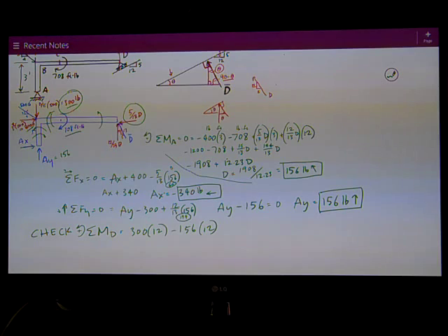I should probably reverse this arrow on my free body diagram for AX. It's going to the left, which is going to create clockwise rotation about point D. So it's clockwise, so it's negative 340 times 3. And then I've got to consider that 708, which is also clockwise, doesn't matter where it is located. So it's negative 708. So I can do all the math, and I get, this is 3600, and I didn't do the math here. Anyway, that all works out to be 0, so check.